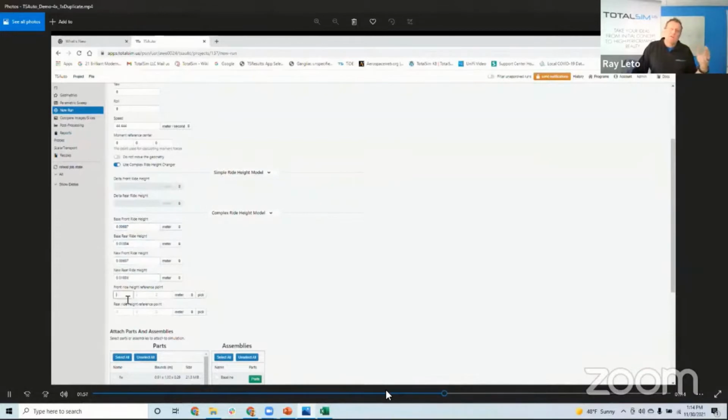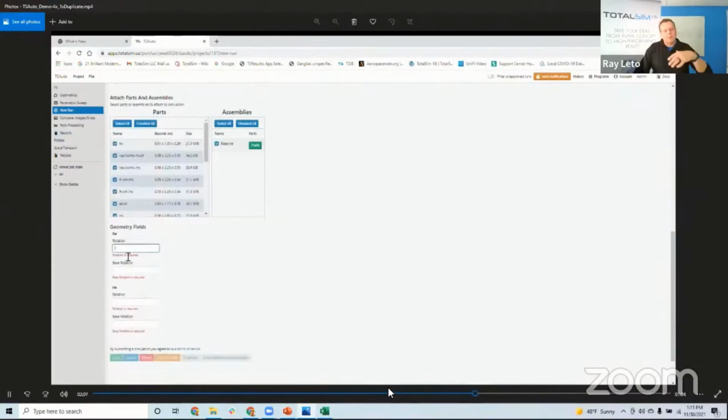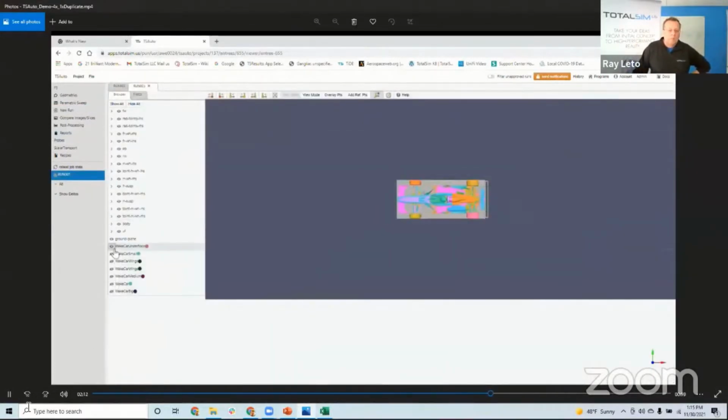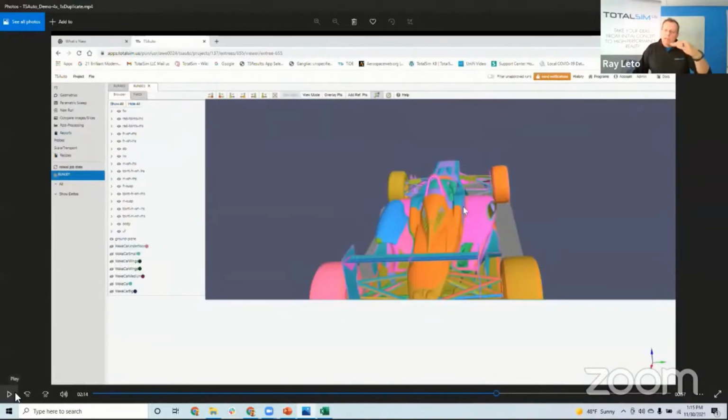And for race cars, typically with a formula car, even sports cars, this ground clearance and where we're holding the attitude of the car is critically important to the aerodynamics. So that's why typically when we talk about mapping, we're talking about what it's like in relation to the ground or the air. And especially with a formula car like we have demoed here, that ground clearance is critical and changes the aerodynamic performance hugely. So we have to be very conscious of it, and we're talking down to millimeter type accuracy here.